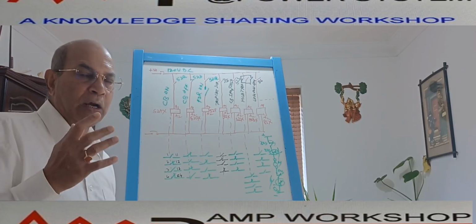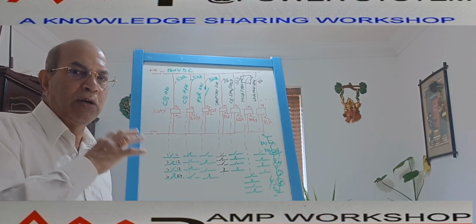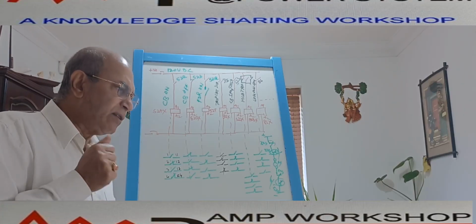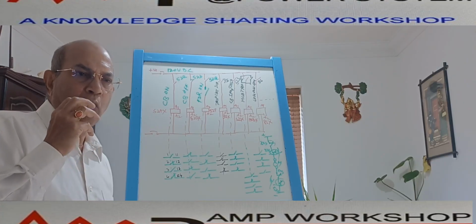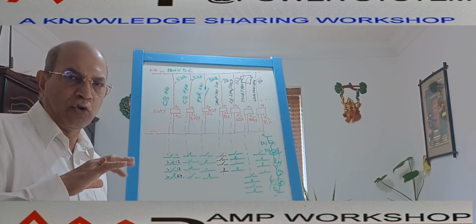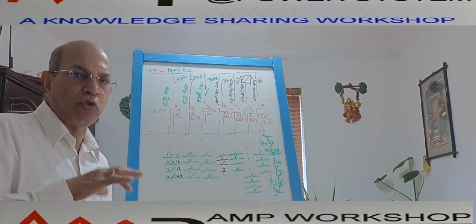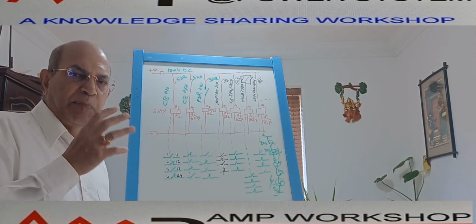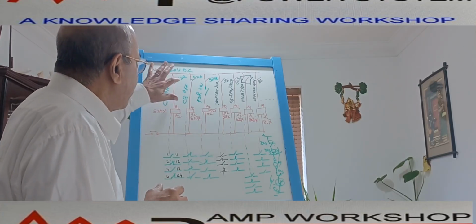Most circuit breakers use this type of auxiliary contact for these functions. First, we consider the breaker on and off condition, meaning whether the breaker is closed or open. So we have seen the breaker auxiliary contact. There is the 52A breaker auxiliary contact for the closed condition.